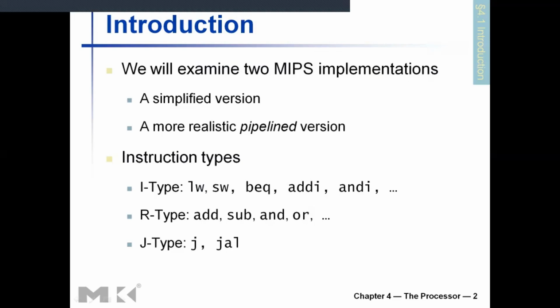In ARM, data processing instructions were mostly arithmetic and logic instructions where you perform operations on data. Then data transfer instructions dealt with memory, reading and writing to and from memory. Then flow control instructions were about manipulating the execution of the instruction sequences, like branches and loops, if conditions, implementing those things. So that is how we categorize the ARM instruction set.